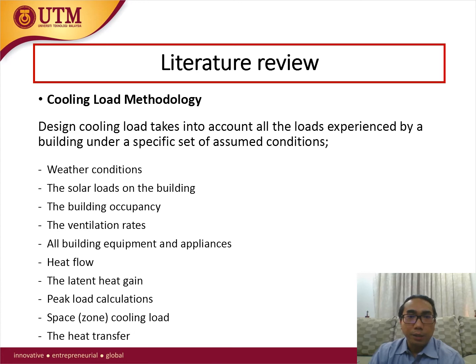Latent as well as sensible loads are considered. Heat flow is analyzed assuming dynamic conditions, which means that heat storage in the building envelope and interior material is considered. The latent heat gain is assumed to become cooling load instantly, whereas the sensible heat gain is partially delayed depending on the characteristics of the conditioned space. According to ASHRAE regulations, the sensible heat gain from people is assumed 30% convection, instant cooling load, and 70% radiative, delayed portion.